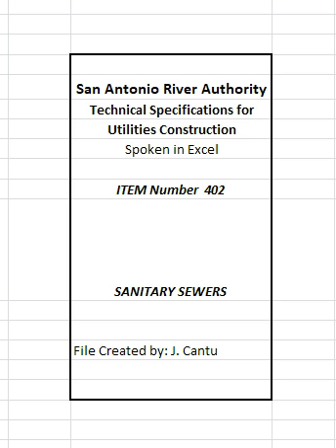2. Where ductile iron pipe to be laid is larger than 24 inches in diameter, the trench bottom shall be shaped by fine grading to firmly embed the lower quadrant of the pipe. At the direction of the engineer, the contractor shall provide a template for shaping purposes. For flexible pipe and as an alternate to the above for ductile pipe, the bottom of the trench shall be excavated, undercut, and the lower quadrant of the pipe embedded in approved select bedding material in conformance with item 404.2a, Bedding, in accordance with lines and thickness as specified herein.